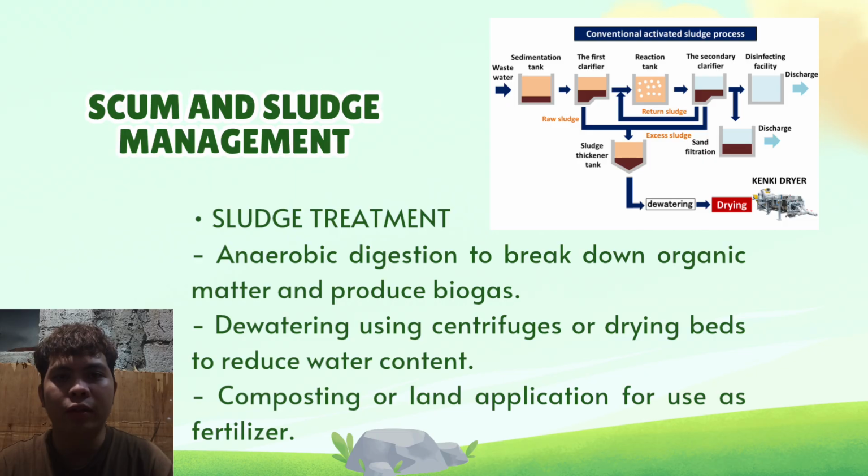And dewatering using centrifuges. Even after digestion, a significant amount of water remains in the sludge, which makes disposal ineffective. Centrifuges use centrifugal force to quickly spin sludge and remove particulates from water. Because less sludge is produced, disposal and transportation are more economical.